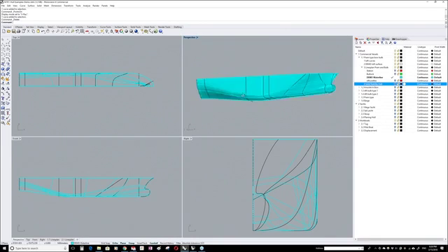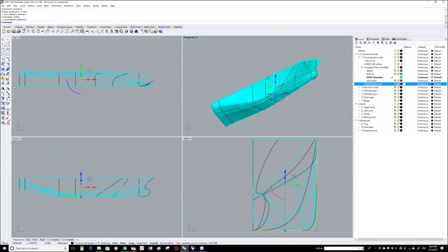The question is, is it also possible to expand the curves to the outside of the bounding box of the half ship? And yes, it is possible. For example, if you take one of the curves and bring it outside, I can later cut this off. It's something we often use for more complex ships: we loft it to the other side and then cut it off to get more difficult shapes.